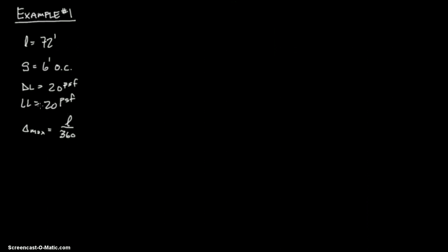We can go ahead and figure out what that is right now. Remember, when you're doing L over 360 or whatever, this L is in inches. So what you have to remember to do is 72 foot times 12 inches per foot, over 360. And that is going to be your maximum deflection.